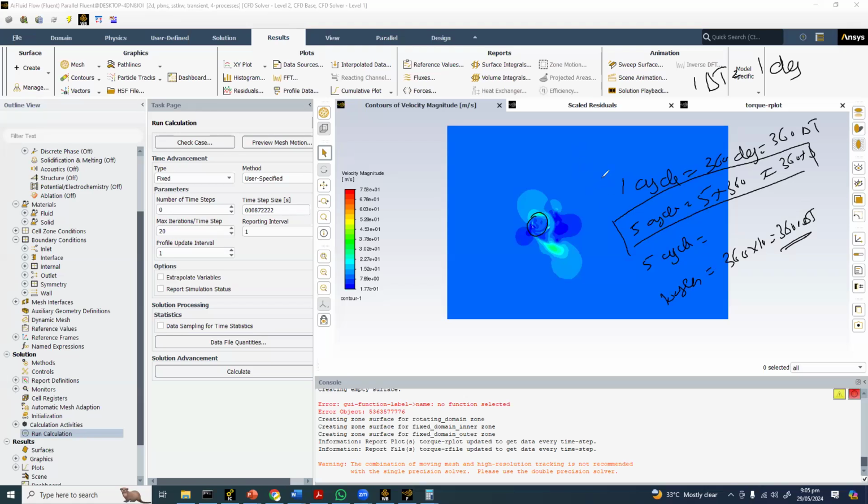Okay. So the question is how we actually assess the convergence for the transient case. The answer is that transient simulation means the solution will be varying with time. Okay. So some variable is here and there's a time here. It will vary with the time. It can vary in any way, but we get this when the graph is a constant change.